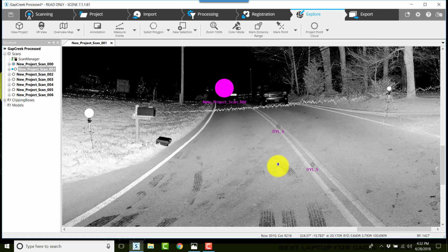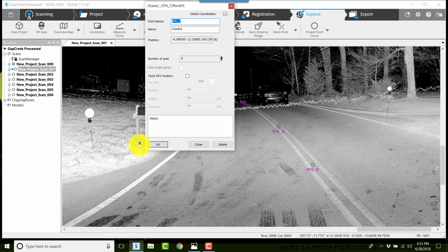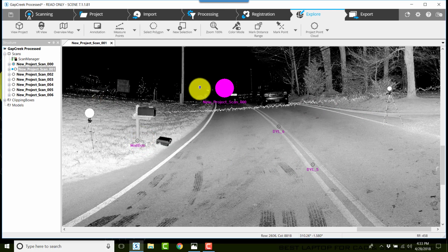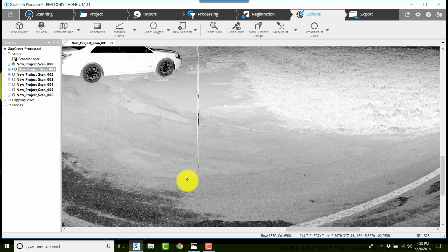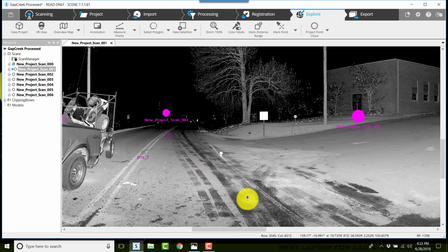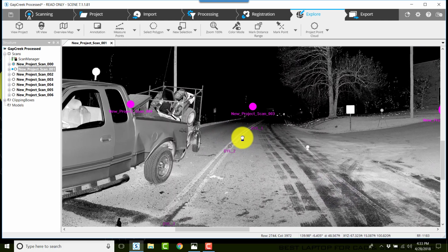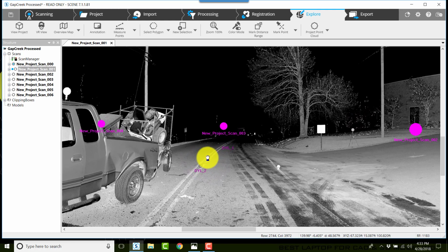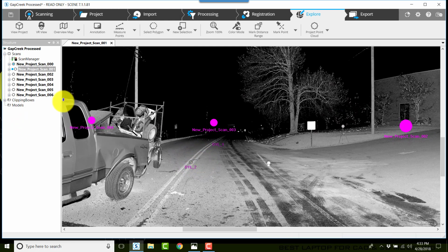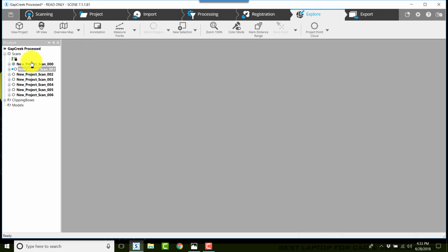So I can follow the protocol for total station mapping, and that is measure like you draw and always finish what you start. We can come back and finish drawing the fog lines and mark things like the mailbox, any utility poles. We can mark driveway openings, other signs, fire hydrants, buildings, whatever it is that we want to mark. When we're finished, we will close this view.